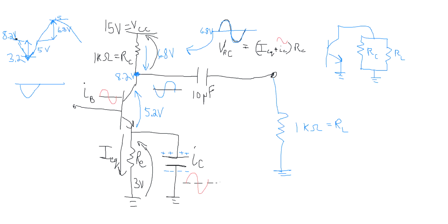Rising above will force current through the capacitor, and this is an AC current. So it's going to create a current through the load. Where's that current coming from? Because we have stopped the current from the collector resistor, and the transistor does not transmit current in the opposite direction. It's like a diode in that sense.